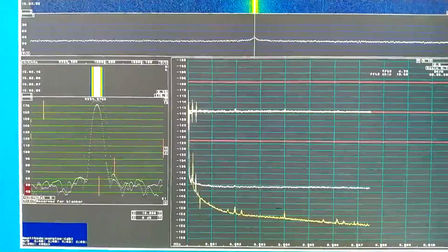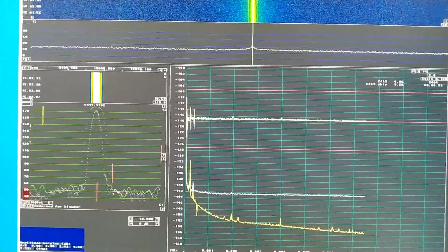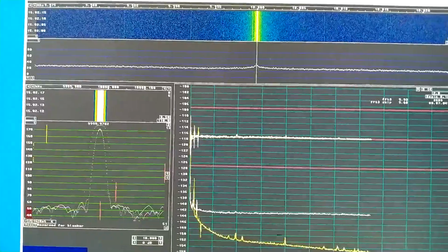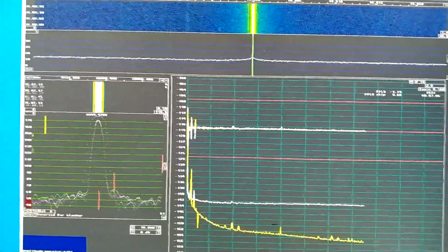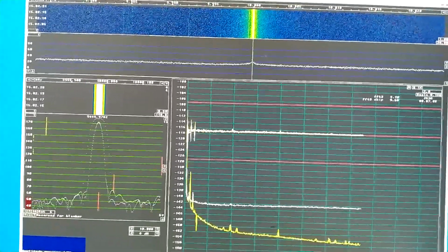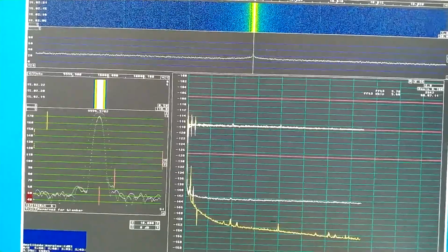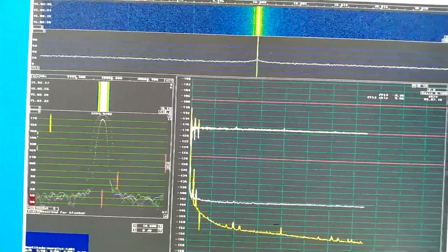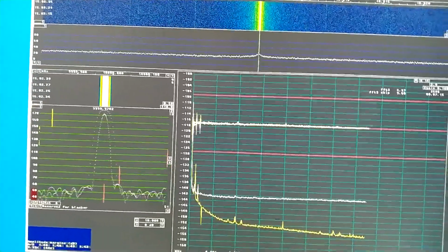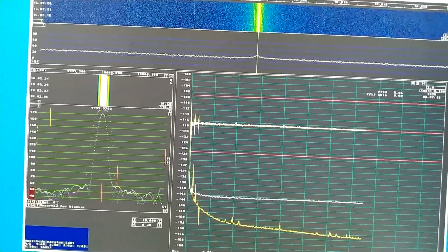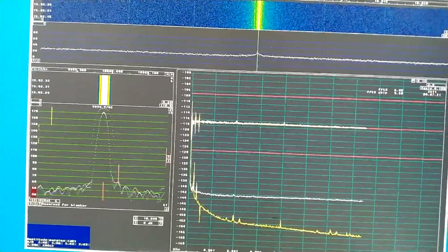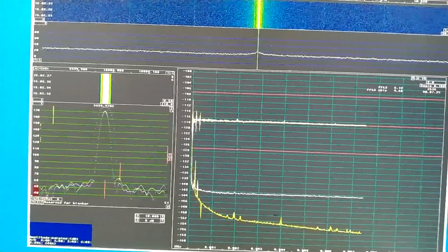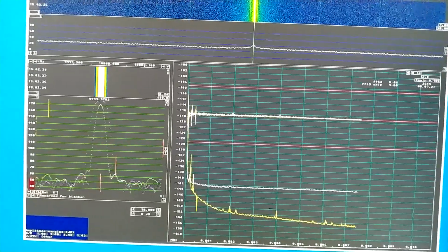This means that with a suitable amplitude detector, one could detect the AM noise of this unit, filter it and phase shift it appropriately, and adjust also by the filter the amplitude, to then add a phase modulator that would produce phase modulation that would cancel the phase noise, the part that is correlated.